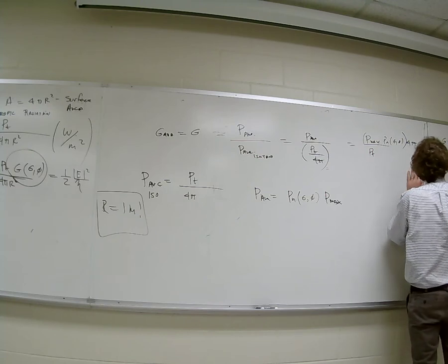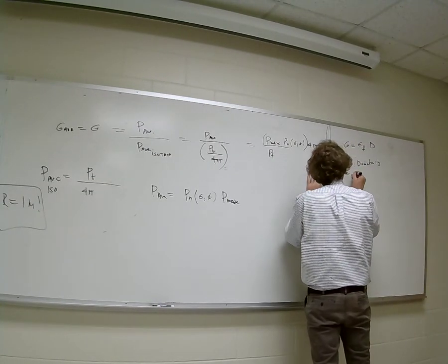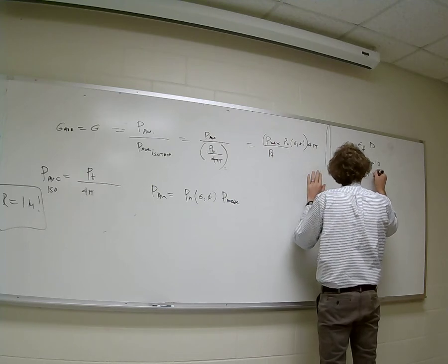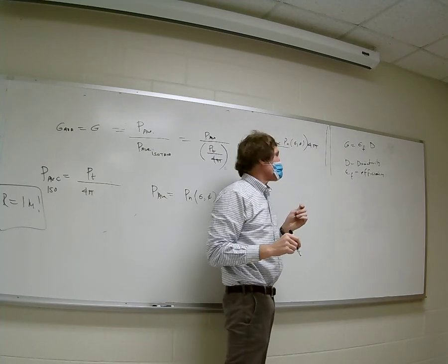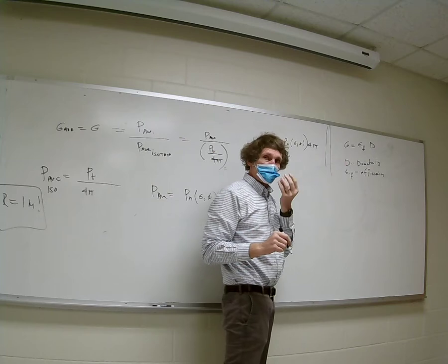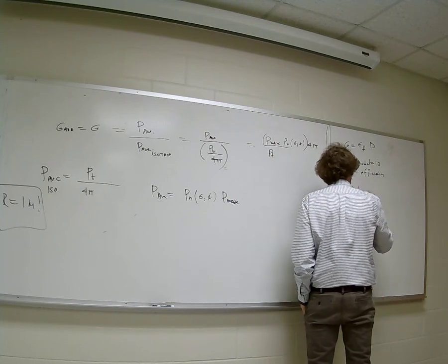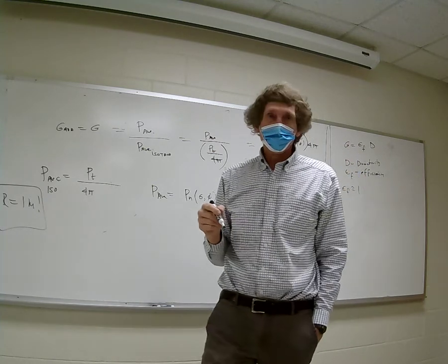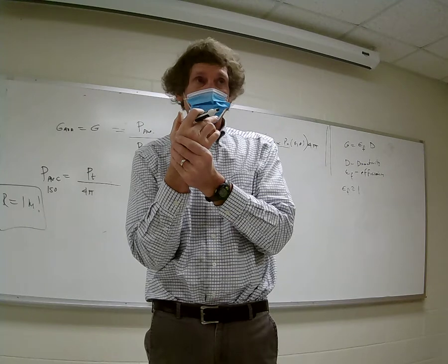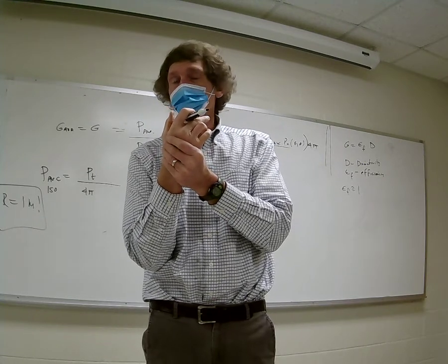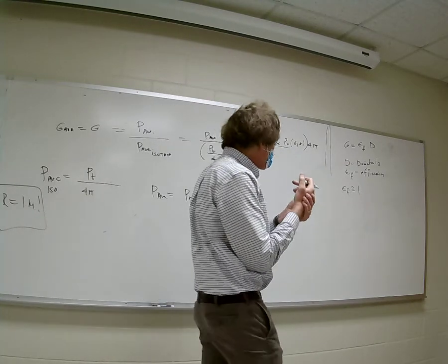Now, D is the directivity, and what I'm calling EF is the efficiency of an antenna. So D and G, the directivity and gain, are proportional to one another, but the efficiency is the key. Typically, the efficiency is about 1. It's about perfectly efficient. It means when you design an antenna and you feed it, you don't have any kind of impedance mismatch. If there was an impedance mismatch, or if there was thermal heating, then the efficiency could go down. For now, just assume it's 1, and that means,